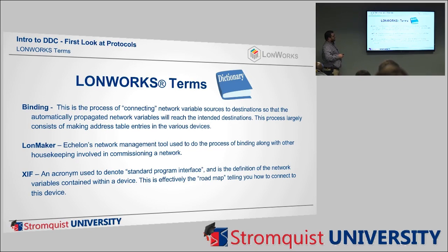Another term you hear a lot in LON is binding. This is the process of saying these two controllers, I want this output on this controller to be tied to the input on this controller. When I bind those two, it's a software thing where I say, okay, this controller, go get this point from this address. So that allows you to have a temperature from this controller shared with this controller, and if your front end goes down, those two points are still talking and your process is still running. So you don't have to have the front end.